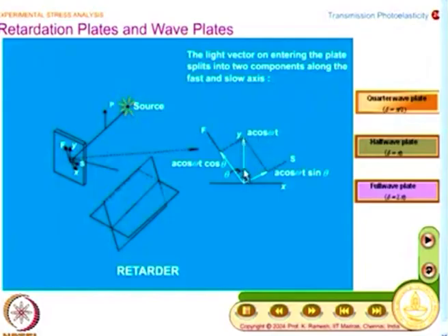This will become two rays within the model, within the crystal plate, and depending on the orientation, one of these amplitudes is longer, another amplitude is smaller. So, amplitude is split, and the planes of vibration are in this direction and in this direction, and they are perpendicular. So, for one beam within the model I will have two rays,